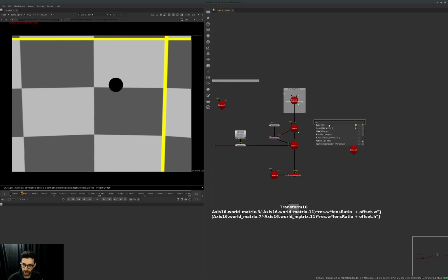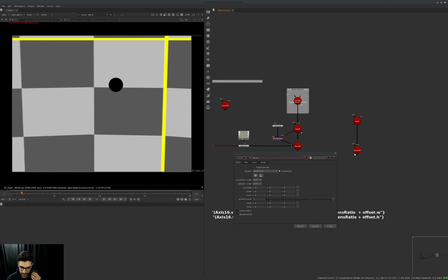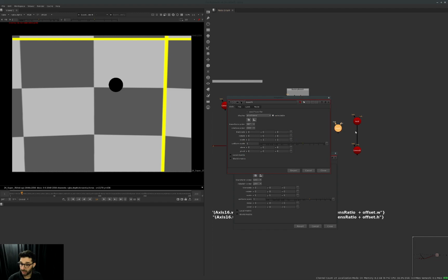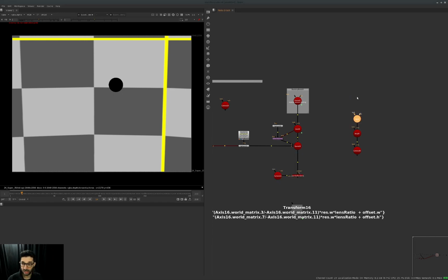It will work. Actually, you know what? I will explain it in a minute. Actually, it will be maybe easier. If you do have concatenation axis and you do want to make it work, it's tricky, not because it's complicated, it's just a bit annoying to do it like that. Let's say I have 3 axes over here and I want to flip the order. Let's say this one doesn't have any animation. Everything is driven by those guys. Do the same thing. Negate all the values of the position and rotation, flip this sign, and also flip the order of the axis. And that would also do the same effect.